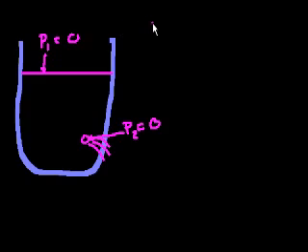You can almost view it as maybe the atmospheric pressure at that point, but since we're in a vacuum, that pressure is 0. And that might have been a little confusing to you, because you said, well, wait, I thought at depth, if I had a point, let's say at that same height, that I would actually have a pressure at that point of rho GH. And that's true. That's completely true. You do have an innate pressure in the liquid at that point of rho GH. And actually, that's what's causing the liquid to come out. But that's actually taken care of in the potential energy part of the equation.